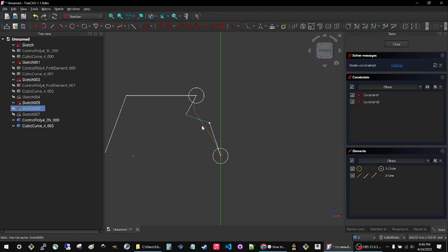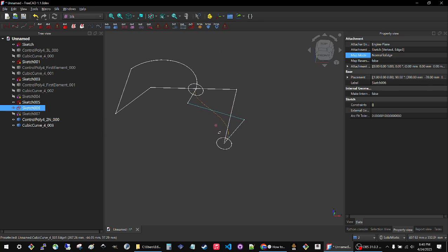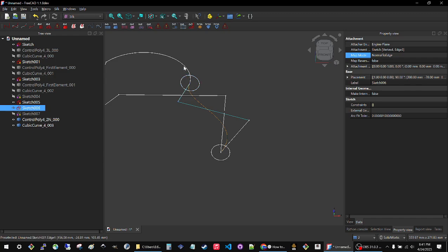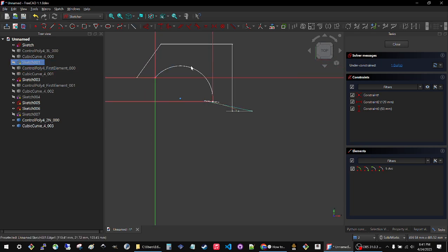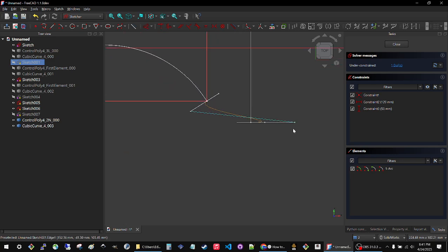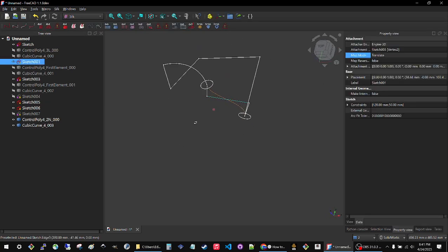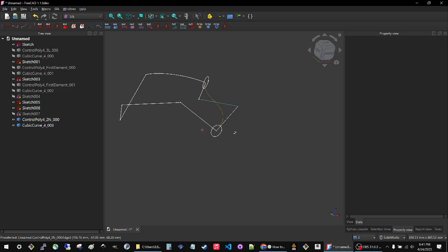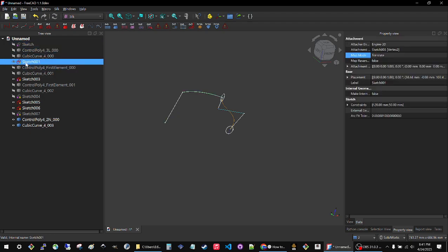Let's do the other one. See right here. See right there. You might say, oh, you're saying they're 3D, you're saying they're not in the same plane, but I'm not sure if that's true. They kind of look like they're in the same plane. Let me show you. I go back to this sketch. I edit it, and I'm going to grab this, and I'm going to go like this. Look, do you see how this sketch is following here? And now you can really see that they're not in the same plane. So I have a completely 3-dimensional curve that is defined by 2 2-dimensional sketches. And so now let's do something fun. Let's hide all the sketches.